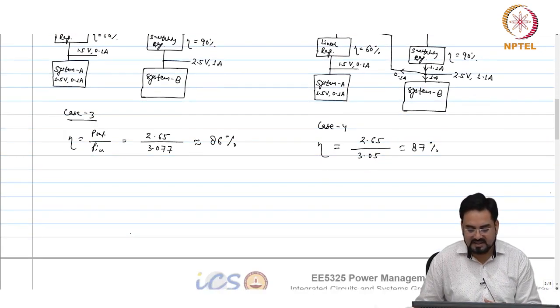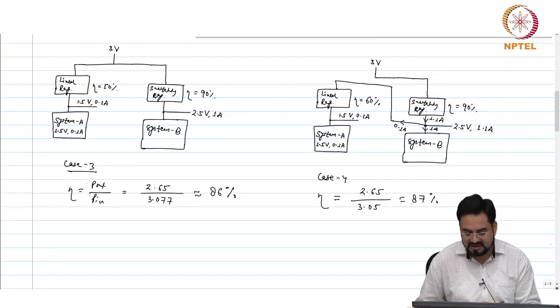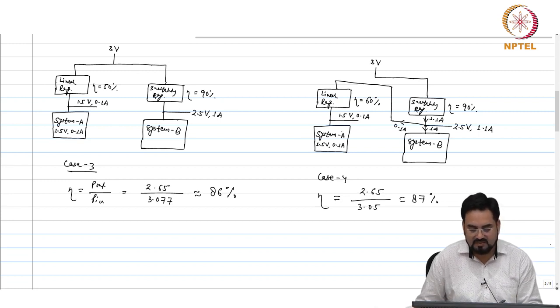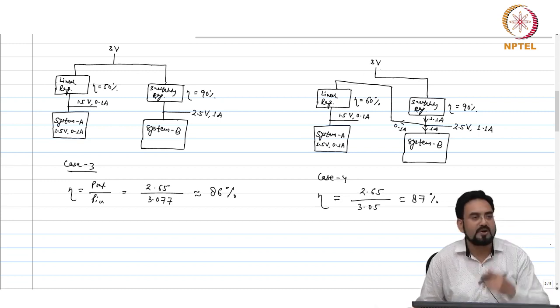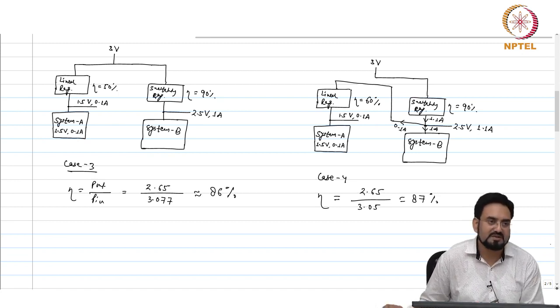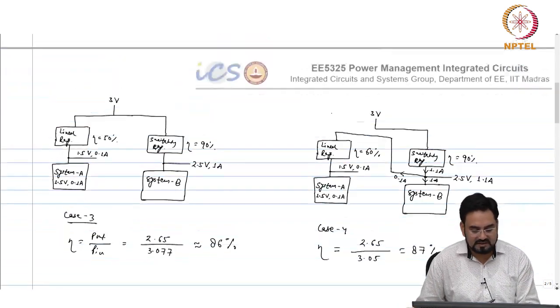Similarly, you can consider a case where the voltage might be different. So, let us say instead of 1.5 volt, the output required is closer to 3 volt, let us say 2.8 volt here. Then we can straightforwardly drive from 3 volt directly, and because my dropout will be only 200 millivolt, we may not bother much about that.